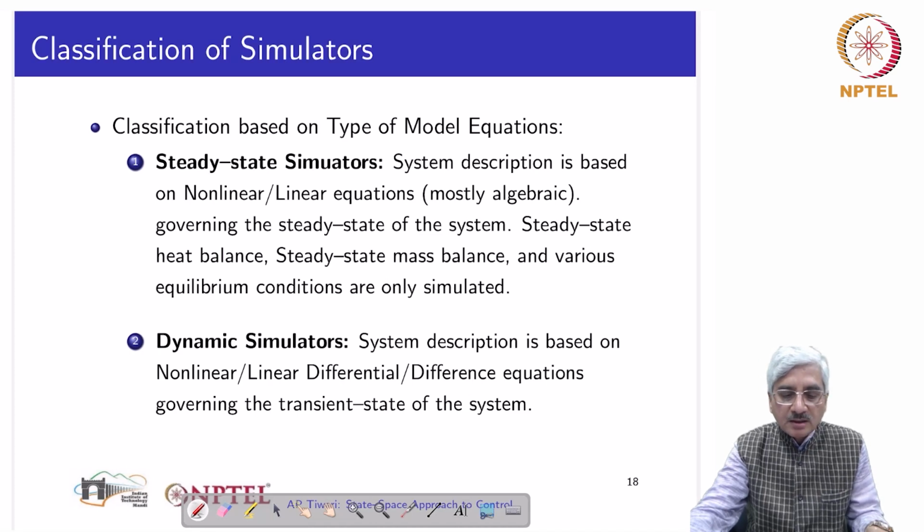So one can use only steady state models and make steady state simulators. The system description in this case is based on nonlinear or linear equations. Most of them are algebraic. These equations govern only the steady state of the system. Steady state heat balance, steady state mass balance, and various equilibrium conditions are only simulated. The transient conditions are not simulated.